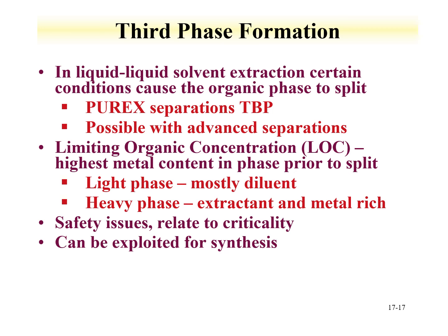We'll end this discussion on solvent extraction, the PUREX process, talking about third phase formation. In liquid-liquid solvent extraction, certain conditions can cause the organic phase to split. For instance, we'll give examples for PUREX type conditions in tributyl phosphate. It's also possible with other advanced separations. One term that's used to define where the split occurs is the limiting organic concentration. It's the highest metal content in a phase prior to the split.